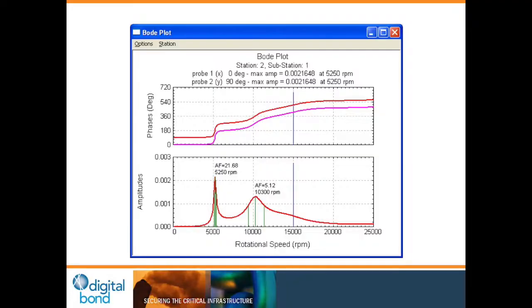This is an example of a rotating shaft and its RPM band. The y-axis here is the amount of vibration seen in the equipment, and the x-axis is the RPM. It has a peak vibration level, and once you go through that peak, vibrations settle down, and then usually there's some kind of harmonic that happens later in the RPM range.